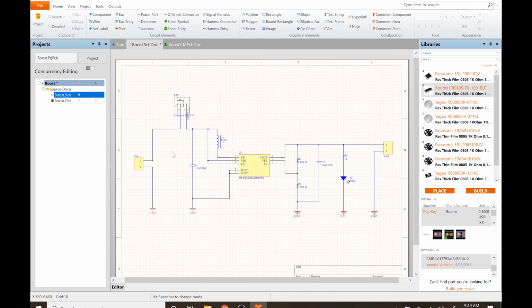So again, this schematic symbol is just the logical connection. It's just the electrical flow. So this is not how the physical pinout is. Pin 1 would be up here and go down to pin 4, hop over to the other side, go to 5 and up to 8. Whereas a schematic is just a logical representation of the functionality. So you can see even the device goes from left to right. The voltage input is on this side and the voltage output is on the right side.